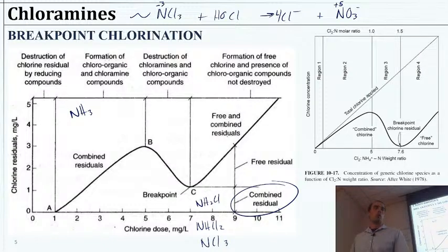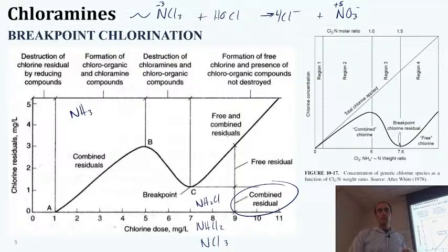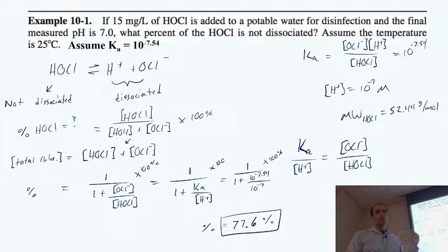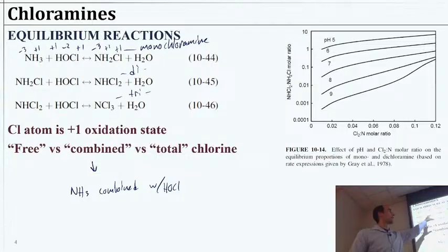Okay, so I don't know if we will, having 4+ equilibrium reactions does get pretty complicated. Probably not going to be taking this level of analysis, applying it to this system necessarily, but we might do some equilibrium equations to kind of see under one particular condition how much mono versus dichloramine we might have.